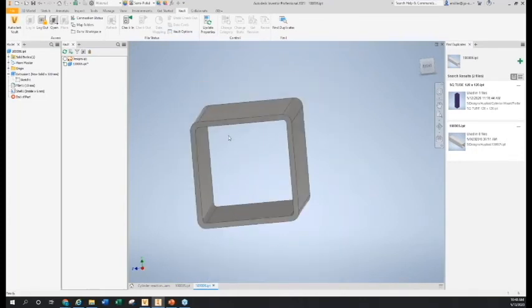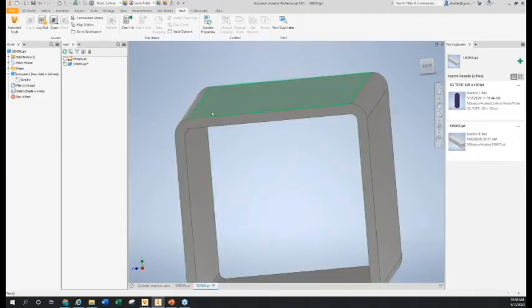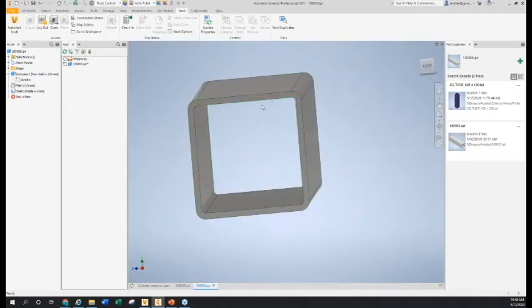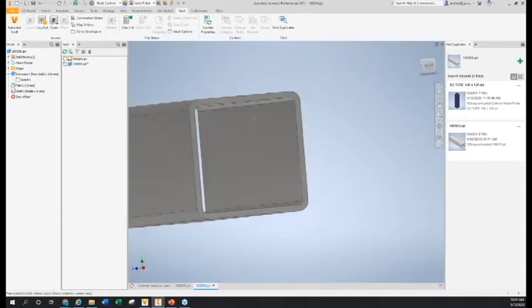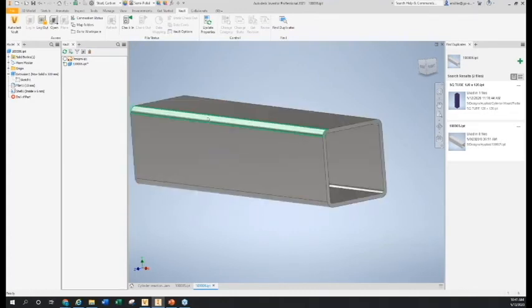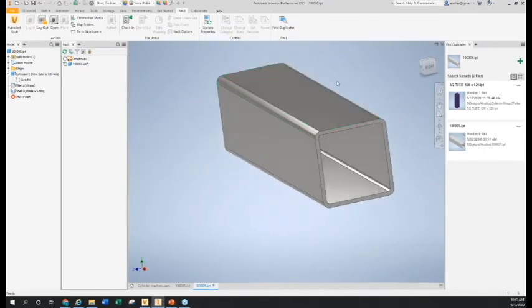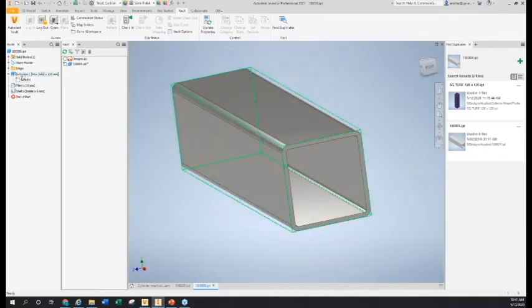In fact, the best way to create tubes would be to use the content center, or maybe iFeatures, things like that, where the shape is already there, and you just give it a depth or whatever. Instead of trying to sketch all these out yourself, especially if they're standard parts, frame generator is another good one. If you're creating a frame with tubes or I-beams or C-channel or whatever it is, use the frame generator, and all you've got to do then is create a sketch or use the edges of an existing part, and it'll generate the tube in there for you.